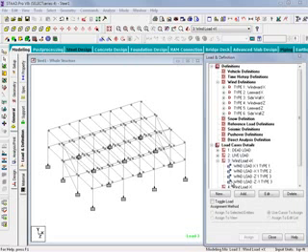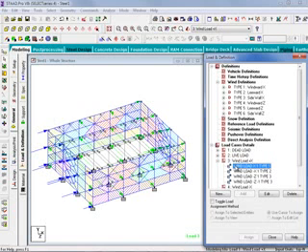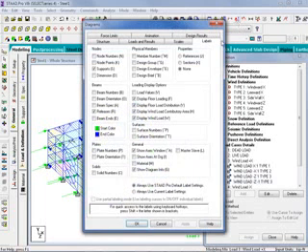We can now see that we've created 4 wind load items within the wind load case for wind load in the positive X global axis direction. These would represent your windward, your leeward, and your 2 sidewalls. If I select each of the load items, I can actually see that, again, this is wind in the positive X direction. Here's my windward face. There are the loads for my leeward face, and I have my 2 side walls. If I wanted to review the load values themselves, I could go up to my Structure toolbar and click on the Symbols and Labels icon and select the value for load values.